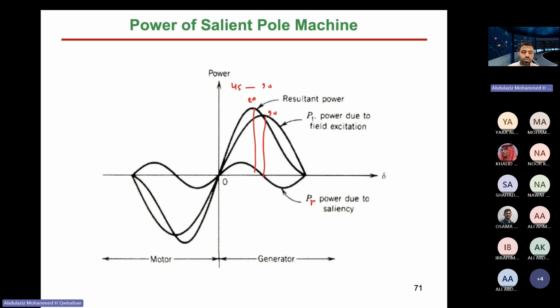Cylindrical, round rotor or salient pole? Round. Round, because its maximum angle is 90 and you're losing synchronism at an earlier angle. Thank you so much, Ali, for answering this question. This question may come in the exam. Clear? So let's take the attendance for now. Remember, this is Ali's question. Study it for the test.